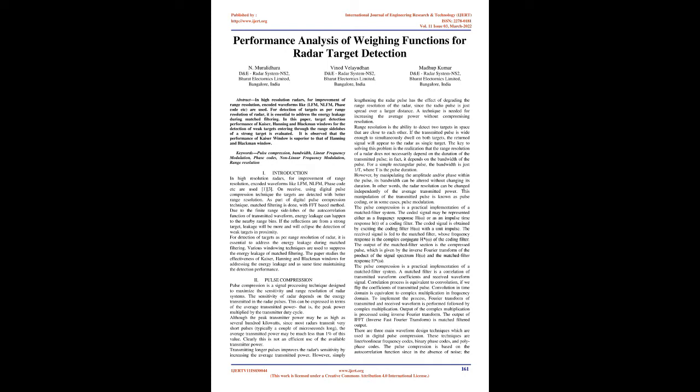Introduction. In high-resolution radars, for improvement of range resolution, encoded waveforms like LFM, NLFM, phase code, etc., are used. On receive, using digital pulse compression technique, the targets are detected with better range resolution. As part of digital pulse compression technique, matched filtering is done with FFT-based method.